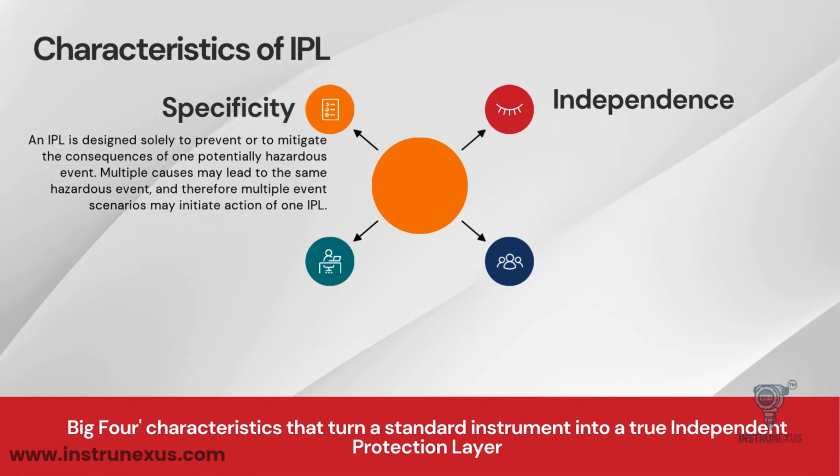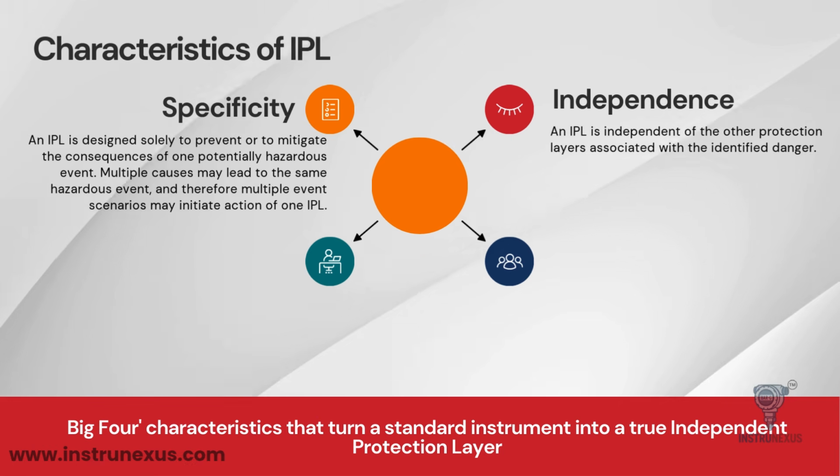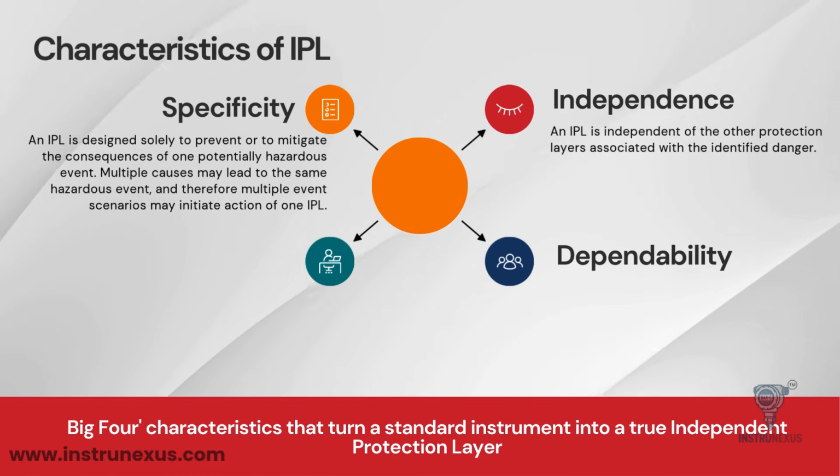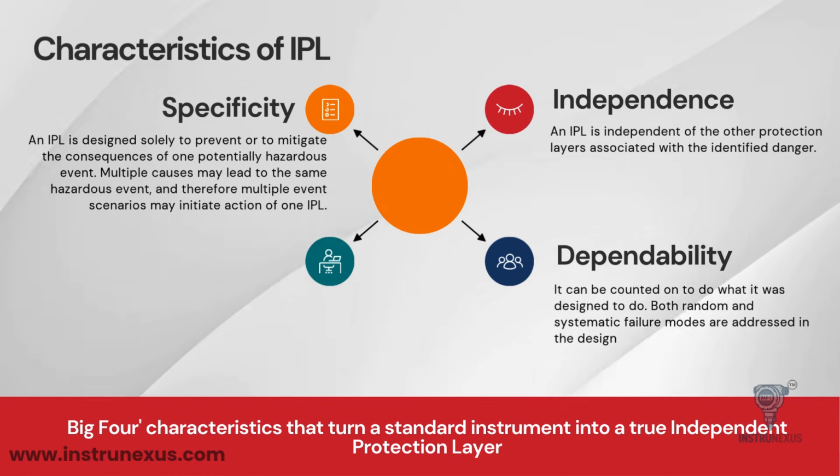Second is independence. This is critical. The IPL must function completely separately from any other protection layers and, crucially, independent of the initiating cause of the danger. Third is dependability. We need to trust it.